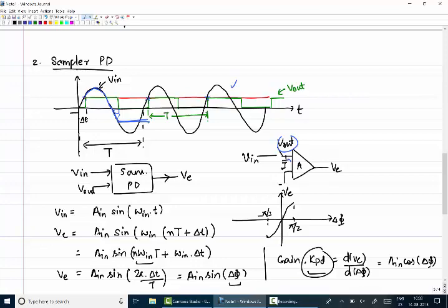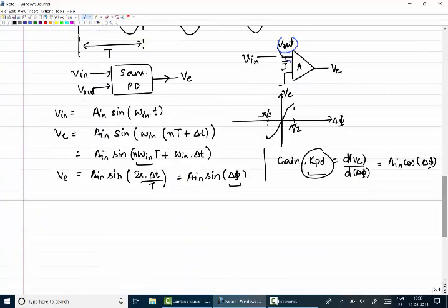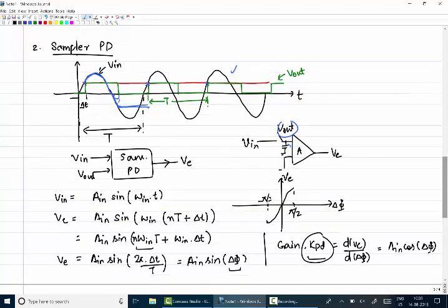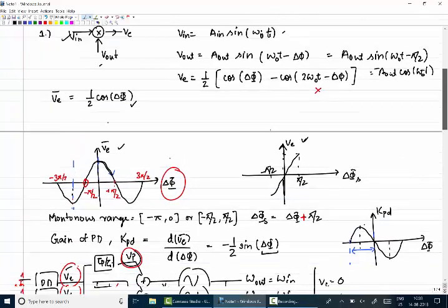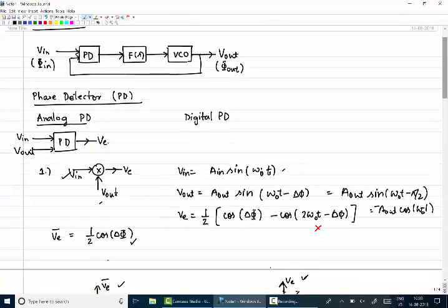Okay, now what happens if you are having any frequency error? This is just for adding to this phase detector. If I have any frequency error, you have seen for a mixer based phase error detector that if I have any frequency error and I am trying to get this phase error detector in open loop, then the V error voltage was doing some kind of asymmetric beats, whatever, depending on the frequency error between the two.